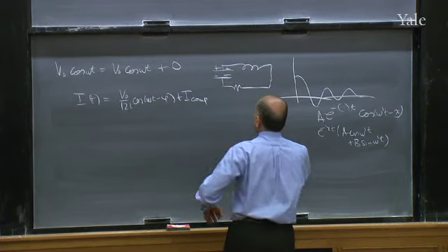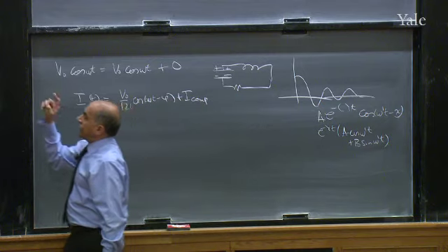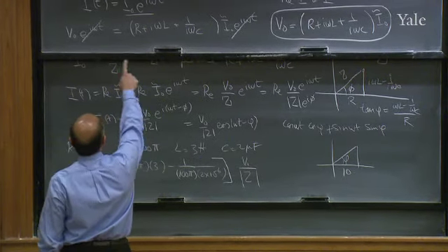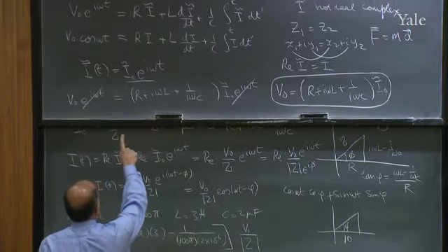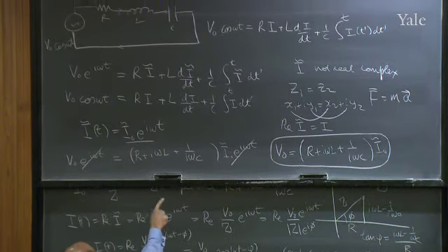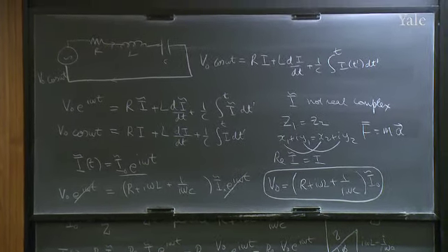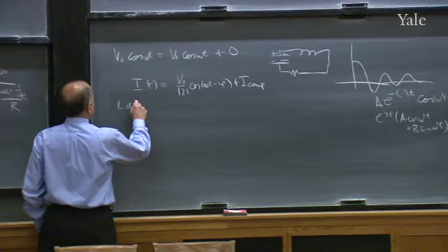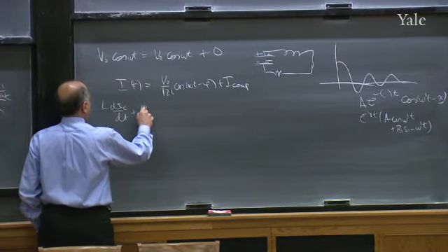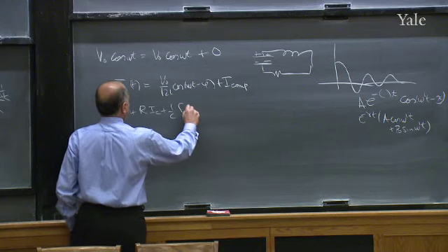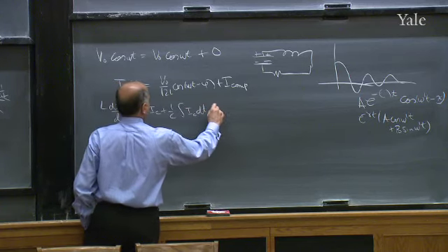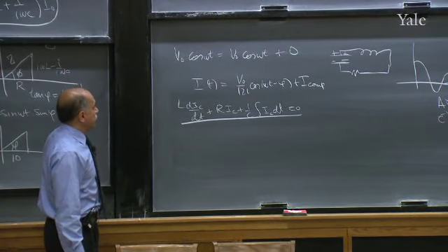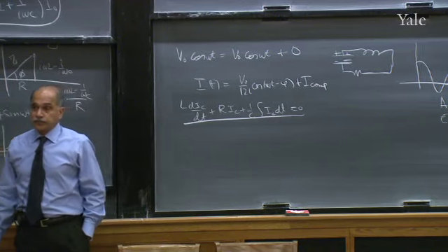Because if you take this complementary function and add it to the equation, you might think it will mess up the equation, but it won't. Because the I that I wrote down will give me V naught cos omega t. The complementary function, when you take R I plus L dI/dt plus 1 over C integral of I dt for the complementary part, you will get 0. Because the complementary guy obeys the following equation: L dI/dt plus R I_C plus 1 over C integral of I_C dt is 0. The equation satisfied in that loop. If it has a non-zero solution, you can add it to your equation.